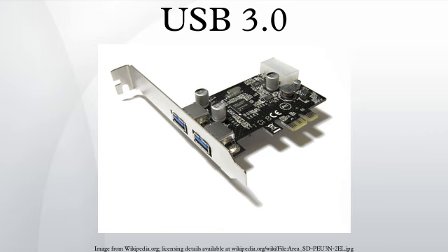On the motherboards of desktop PCs which have PCI Express slots, USB 3.0 support can be added as a PCI Express expansion card. In addition to an empty PCIe slot on the motherboard, many PCI Express to USB 3.0 expansion cards must be connected to a power supply such as a Molex adapter or external power supply, in order to power many USB 3.0 devices such as mobile phones, or external hard drives that have no power source other than USB.